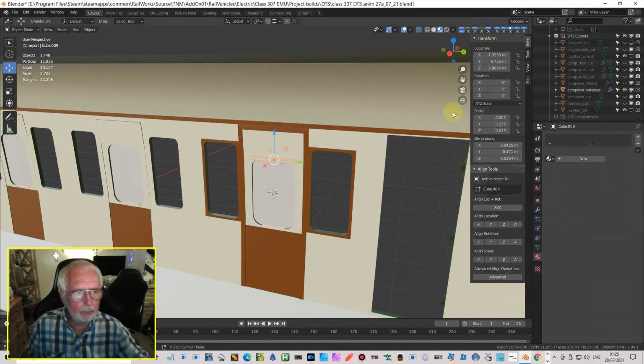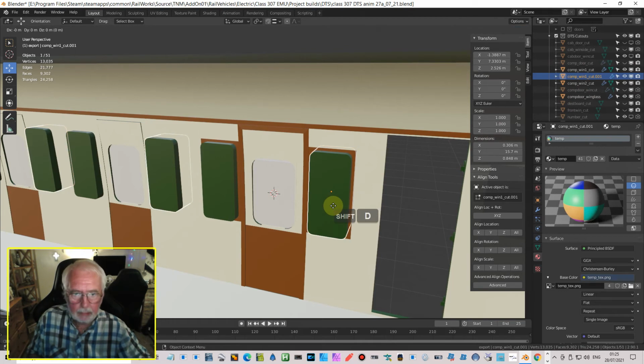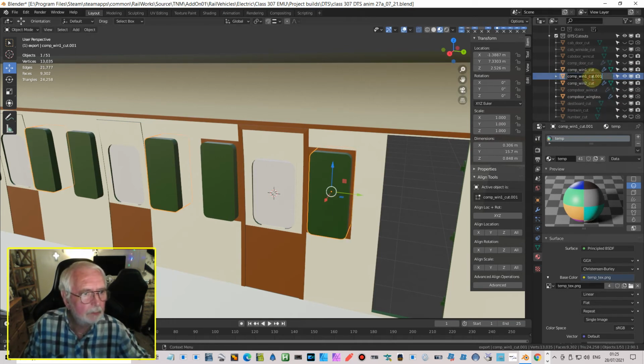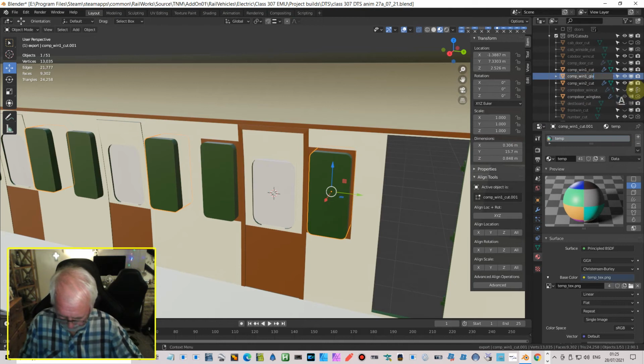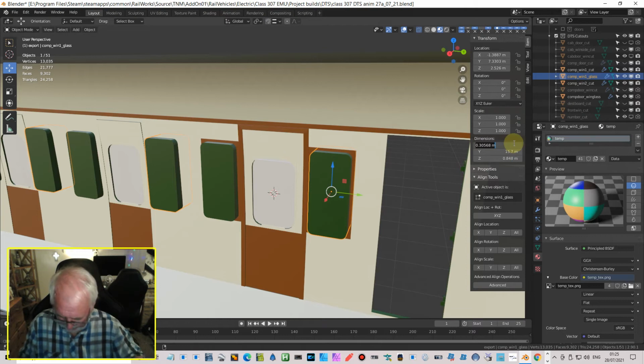And while we've got the cutouts here, let's go Win1 and Win2 cut. Okay, duplicate and call this glass. Okay, and alter this, so X is 0.02, no, I was going to do it in centimeters there, but that would have been an inch, so I said a quarter of an inch, didn't I? 0.25 inch.